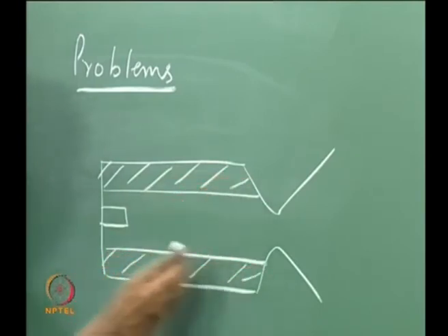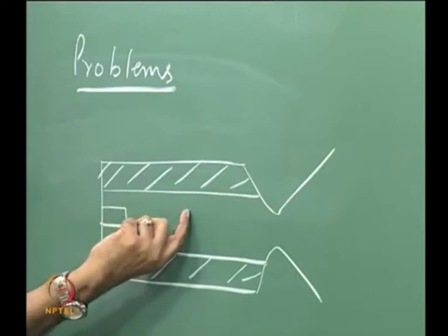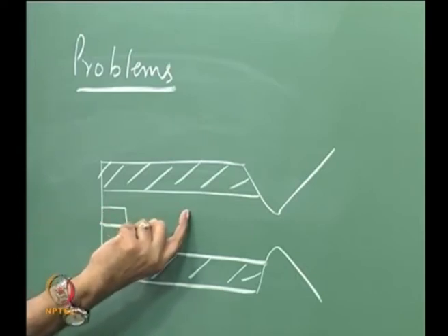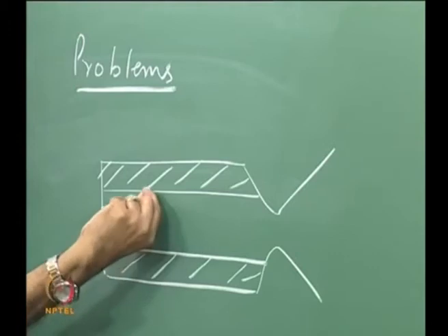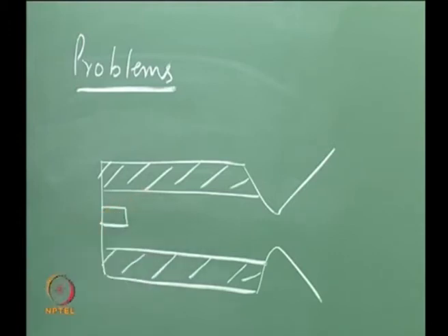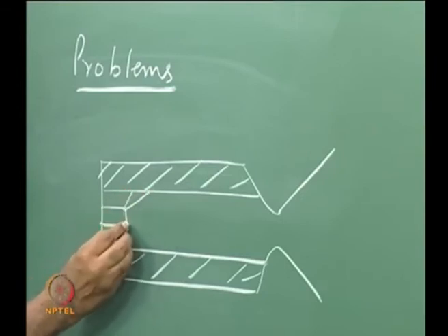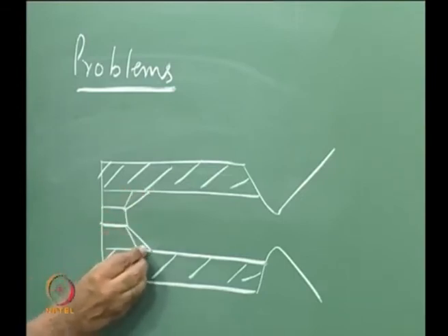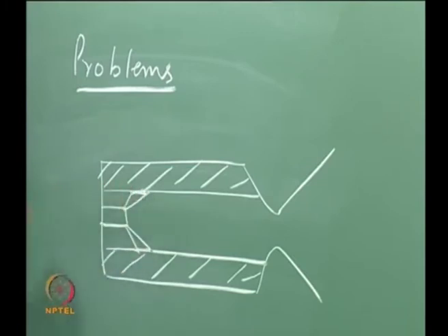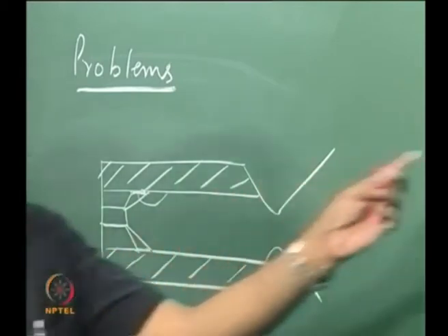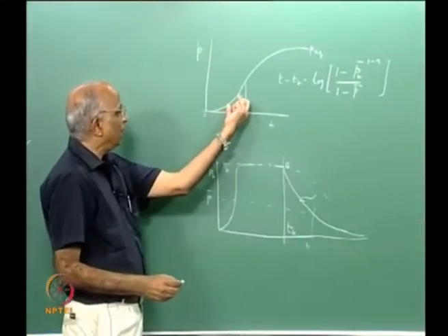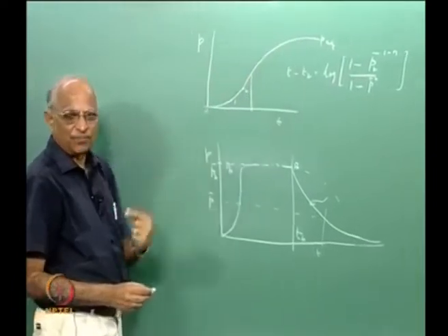Now I make an igniter, and how do we design an igniter? We were very clear, it must pressurize this cavity to some value, not very high, such that a flame can be near the surface, and also give some energy, and we said propellant requires some minimum energy for ignition. I get some plumes and it ignites a particular surface. This is all the requirement, and thereafter the flame spread and pressurization takes place, and we had this particular curve, local ignition, flame spread and the pressurization.